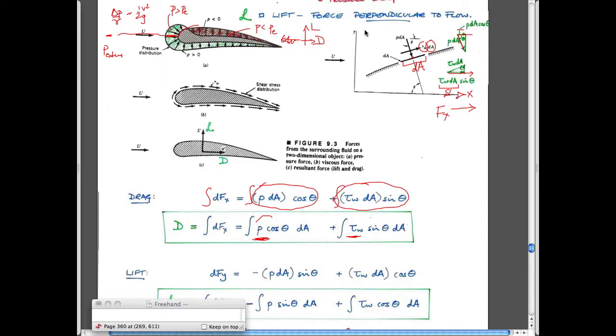And so it's just to reinforce the idea that on a wing, you not only have lift, which is what you're interested in, but you also have some kind of drag as well. You'd like to maximize lift, and you'd like to minimize drag, because obviously you have to push against drag. And to make the point that both lift and drag are due to two effects. One is the pressure influence that causes both lift and drag in this case. And certainly the shear stress has an effect on drag, but there's also a component of the shear stress acting vertically here, which would cause some form of lift. You don't know what the net effect would be, either positive or negative in that particular case, right?